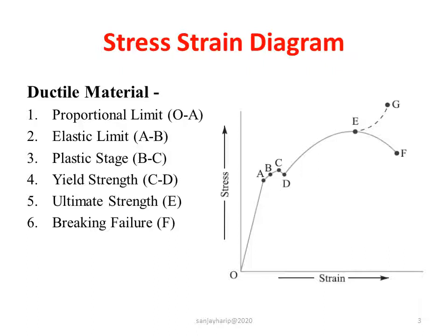In designing various parts of machine, it is necessary to know different properties of materials. The mechanical properties are commonly determined from a standard tensile test carried out on a universal testing machine, which is known as UTM. All of you have very well observed this test in your strength of material course. The resulting values of stress and strain are used to draw this diagram. Therefore, this diagram is known as the stress strain diagram.